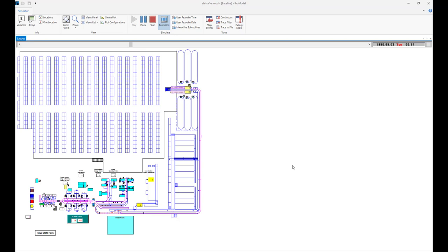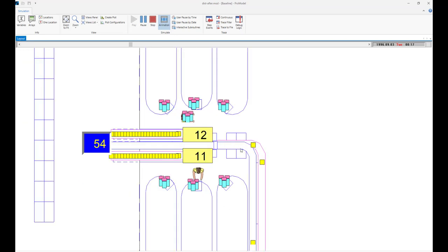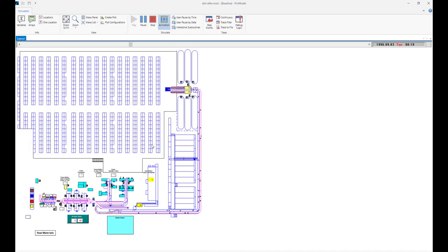Instead of introducing all of the totes at the beginning of the line, upstream from the carousels, they would introduce the totes just upstream from the first pick area on the conveyor. This resulted in 2 new tote induction areas, one at the flow rack area and one upstream of the automatic area. The ProModel simulation model predicted that this change would increase the capacity of the system by 10%. A good increase, but still not enough to meet the current order demand.